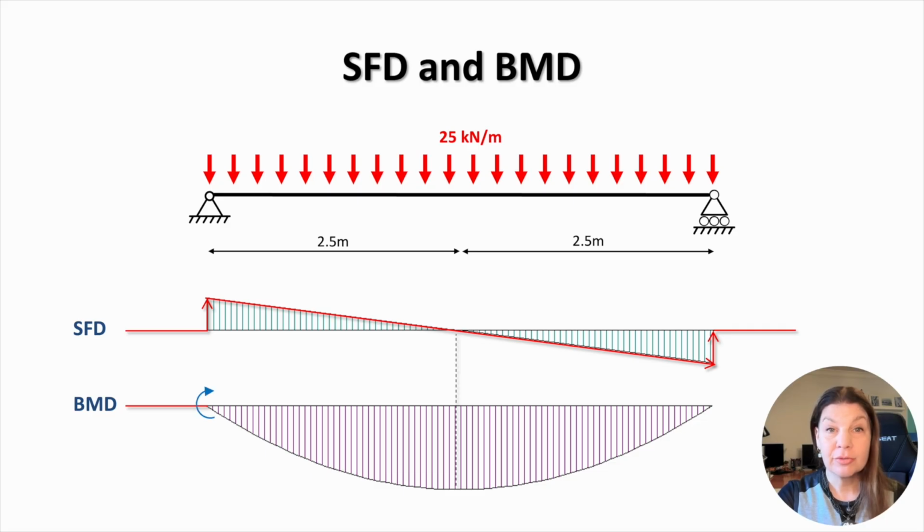At the left support, the reaction force makes the diagram change direction. Since the reaction force acts upwards, the change in direction occurs clockwise. Under the uniformly distributed load, the bending moment diagram curves. Since the uniformly distributed load acts downwards, the diagram gradually curves counterclockwise. The reaction force at the right support makes the diagram change direction. Since the reaction force acts upwards, the change in direction occurs clockwise. On the right of the beam, the bending moment diagram continues at zero level.